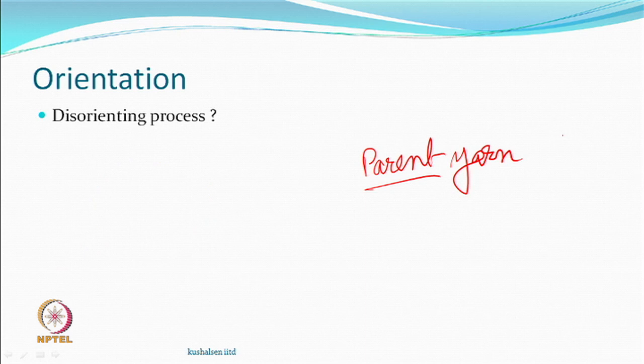So, what do you say? Low. Okay. I just note down, you are saying low. So, how many people believe that should be low? One. So, others do not believe it. You can appreciate when you draw a fiber, you improve the orientation. In what way will it help? If you have higher orientation, what are the general properties which are likely to be affected? So, tenacity may be higher, modulus could be higher. These are the properties you can think will be higher.